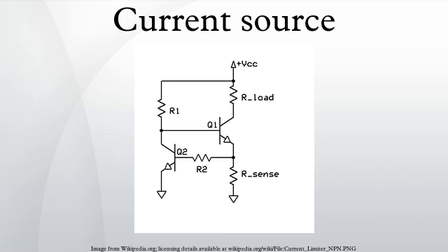The operation of the circuit is considered in detail below. A Zener diode, when reverse biased, has a constant voltage drop across it irrespective of the current flowing through it. Thus, as long as the Zener current is above a certain level, the voltage across the Zener diode will be constant. Resistor R1 supplies the Zener current and the base current of the NPN transistor.